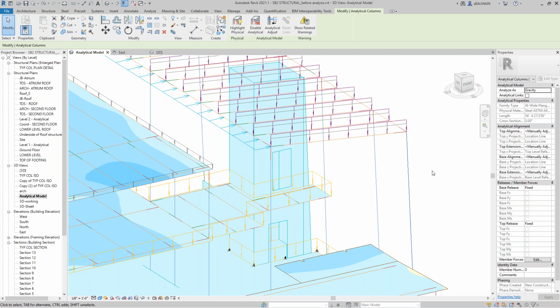In fact, in Revit, if you go from Advanced Steel to Robot, it will take the center line of the profile, and there are no analytical elements in Advanced Steel. So it will be exactly the same.